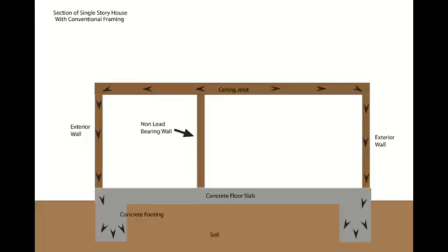A non-bearing wall simply means that it is not going to have a structural footing underneath it, and for the most part, the weight of the building, the roofs, the rafters, the ceiling joists is going to be for the most part transmitted through other parts of the building. And in this picture right here, the weight is still being distributed to the outer exterior walls.